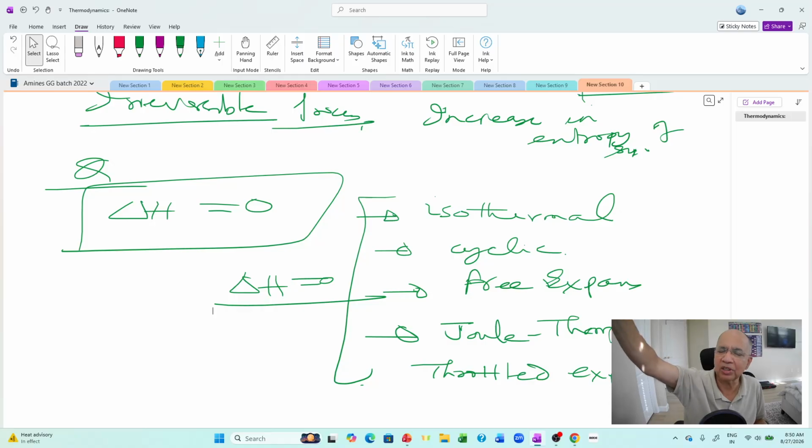The moment you push, gases come out as vapor. It goes from high pressure to low pressure. Suddenly, even if the walls are diathermic, not exactly insulated, it is analogous to a near adiabatic process. So the expansion happens because of its own internal energy. So internal energy will decrease and there will be cooling.